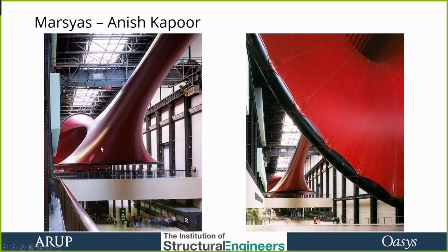And we know that the geometry is correct and the pretensions are correct because these surfaces are smooth. If you get it out of balance in the pretension, the tensions in the fabric, you get wrinkles. As you know, if you ever tried, well, look at my shirt, not quite equal tensions on the shirt. You get these wrinkles. Huygens, or was it Wagner's tension fields? On the two, we get confused between those two.